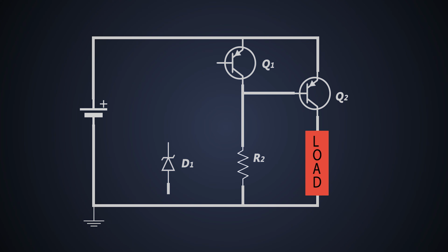When the voltage reaches a certain value, that Zener diode will go into Zener breakdown and current will flow through it. So we'll connect the Zener diode to the base of the transistor and we'll connect a current limiting resistor R1 so that when input voltage reaches Zener voltage, the circuit shouldn't short. And also it will make sure the base of the BJT Q1 is protected from high input current.